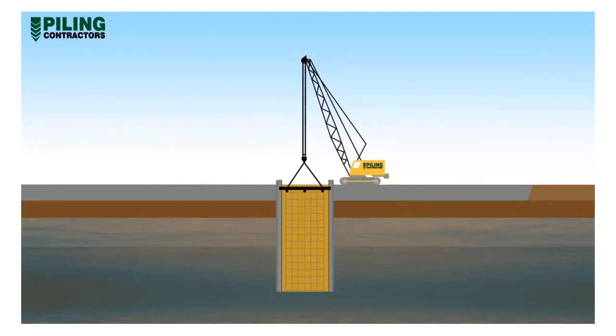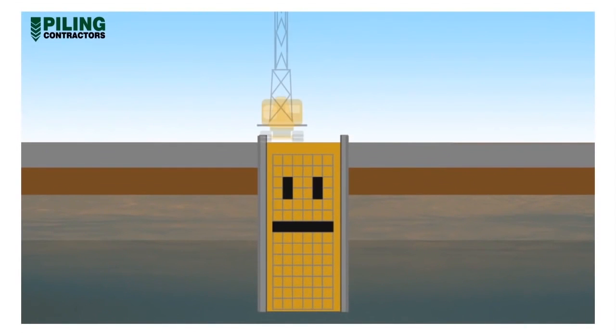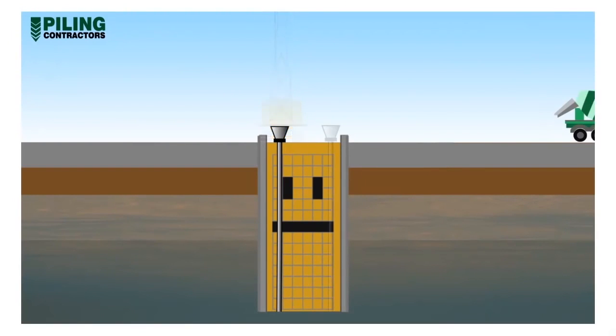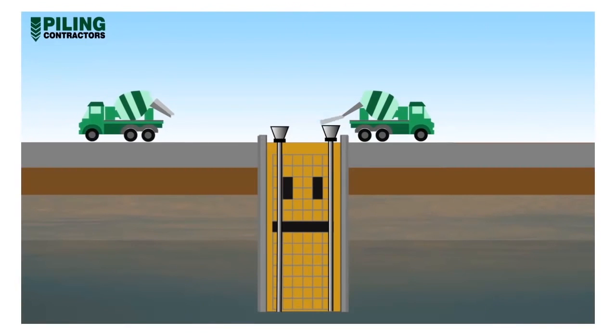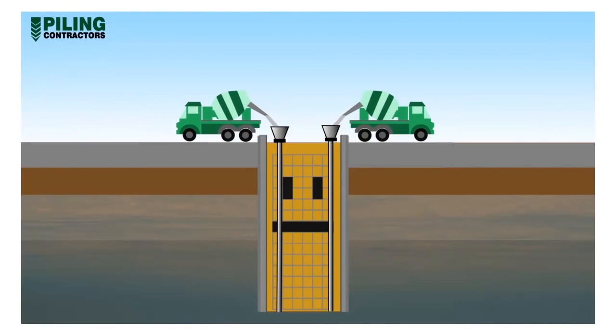Once the earth is excavated, a prefabricated reinforced cage is lowered into the excavation between the stop ends. Blockouts for floor slab connections, ground anchors or other penetrations can be formed in the reinforced cage. Concrete is poured into the excavation using the tremie method. This is achieved by use of a hopper and steel tube extending to the base of the excavation. Typically, the hoppers are used for 6-meter wide panels. The hoppers and tubes are charged with concrete, then the tubes are lifted off the bottom of the excavation so that the concrete flows out.